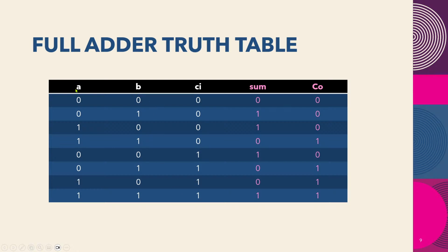And if you look here for this A and B, you've got the exclusive OR for the sum like we saw in the half adder. Well, this is not an exclusive OR. It is the inverse of an exclusive OR. If you took these values and exclusive OR'd them and then took the inverse, you would get these values here, 1, 0, 0, and 1.